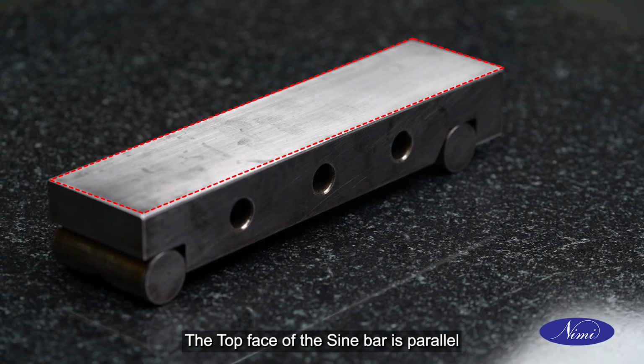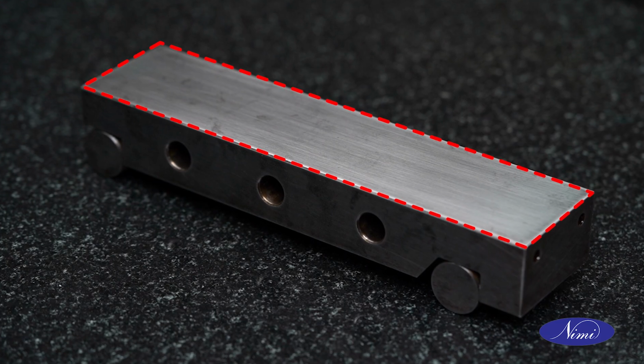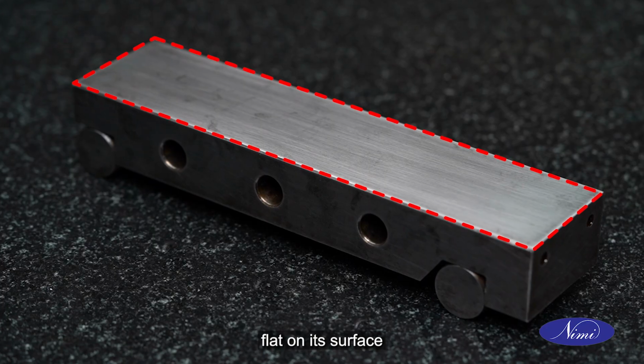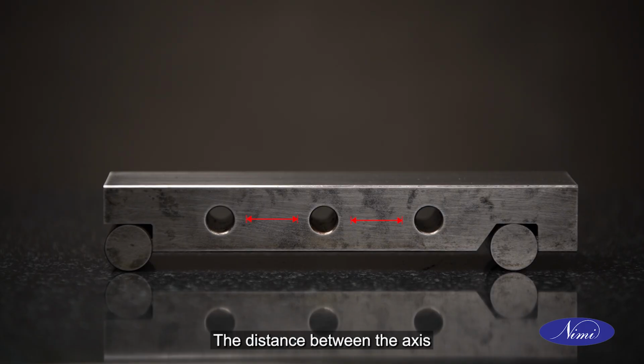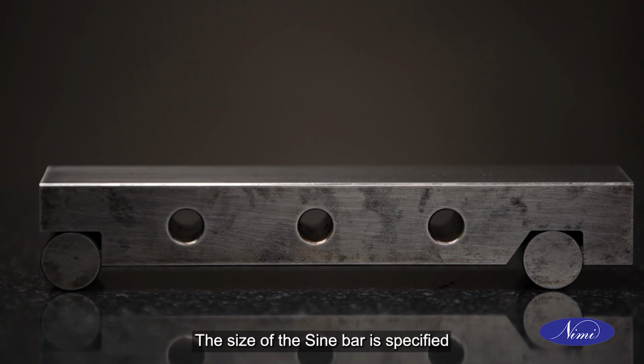The top face of the sine bar is parallel to the surface table when both the rollers are rested flat on its surface. The distance between the axes or centers of rollers is fixed to a high degree of accuracy. The size of the sine bar is specified by the distance between the centers of the rollers.